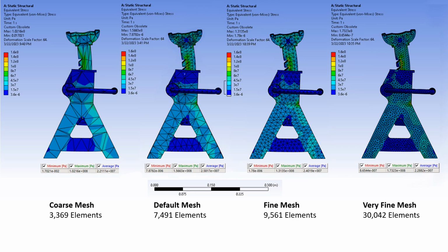As you can see on screen, the default mesh uses mesh elements of varying sizes dependent on the complexity of the geometry area. The 3 mesh types added for analysis use constant mesh element sizes throughout. This makes an imperfect comparison, but still provides a very useful reference point. Ultimately, it was decided to continue analysis with the default mesh as it seems to be the most appropriate optimization of mesh elements. Due to the complex nature of our geometry, TET elements were the type of elements used in our mesh.